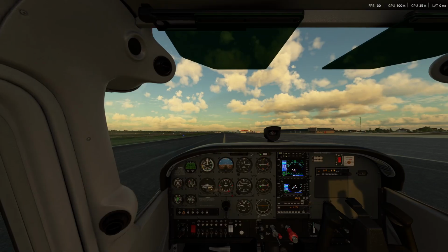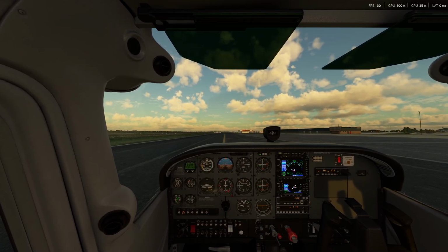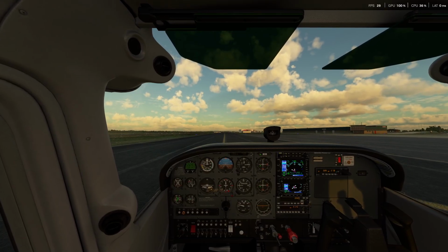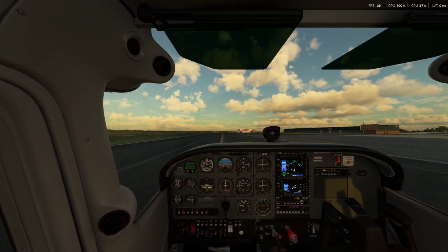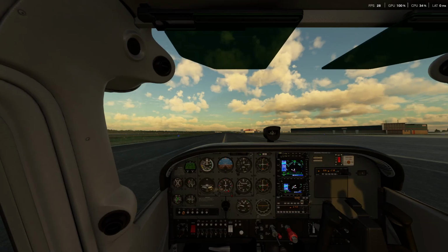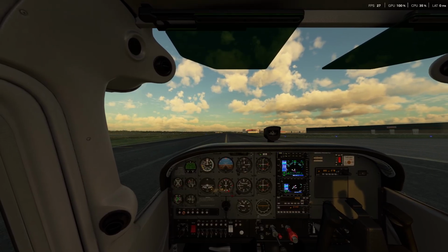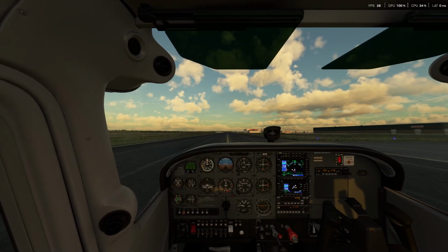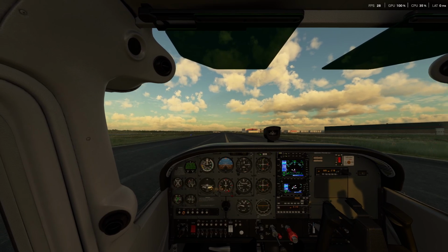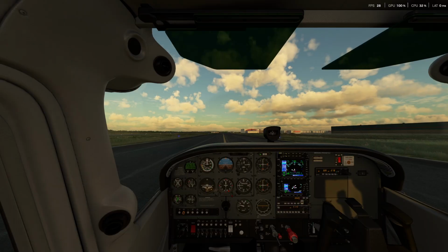Alright, it's going to be a normal takeoff from runway 29. The winds are currently 270, so the aileron control input is going to be to the left during the takeoff roll. Airspeed alive is going to be at 40 knots. VR, rotate, is going to be at 55. The initial climb speed is 74, best rate. If the aircraft is not airborne by abeam of the Monkey Flight College, just behind us to our right side, I'm going to abort the takeoff and make a radio call. But again, the radio call is not going to be required because we don't have ATC on.